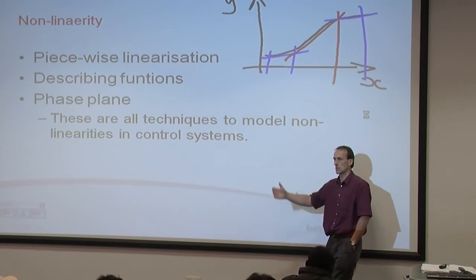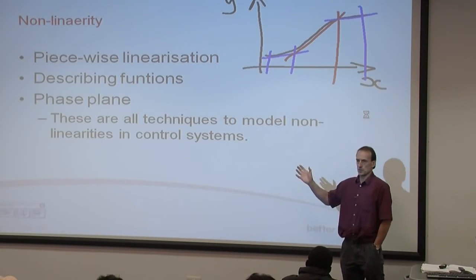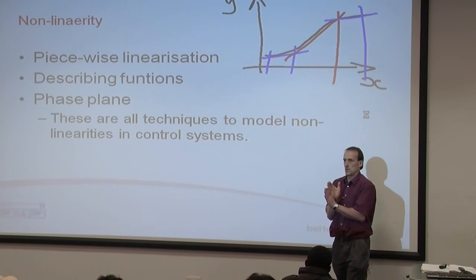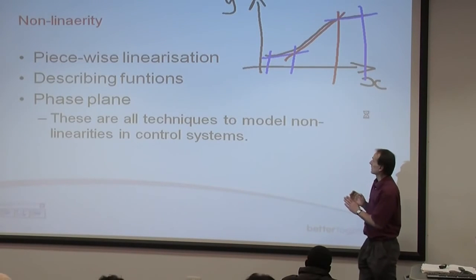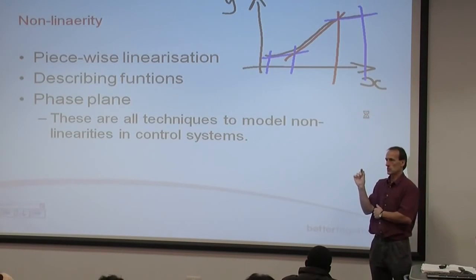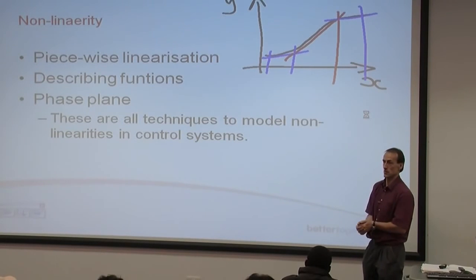If you think of things like process technologies in pharmaceutical industry, food industry, you're trying to control temperatures in many cases to a fixed point. So really, in lots of cases, although the systems might be non-linear, your controller's trying to keep them around a fixed point so you can pretend it's linear just either side of that point.